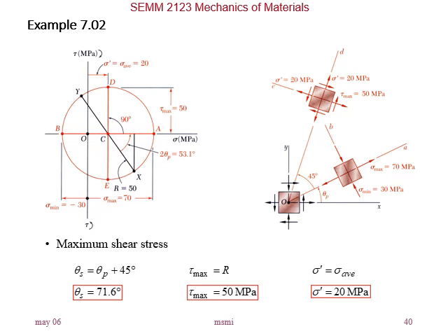Now, if you want to find the maximum shear stress, again it's the same rule. You can go from A, from the plane for principal stress, it is 90 degrees away, right? To get to the top point D there.